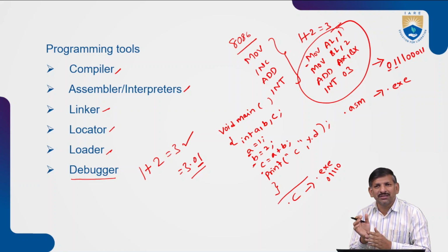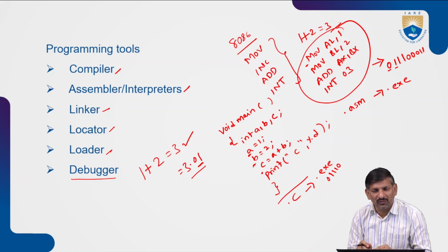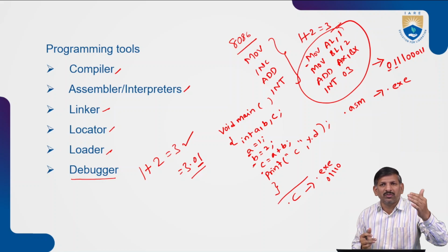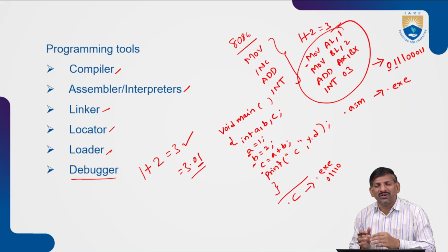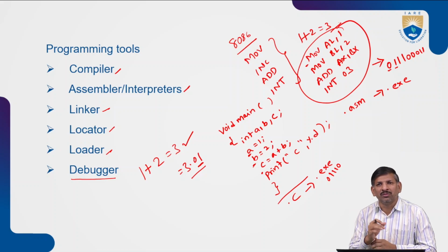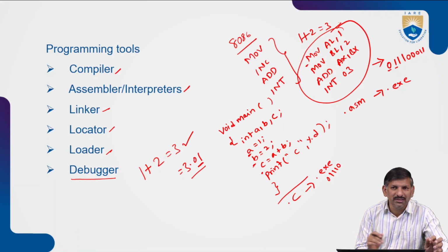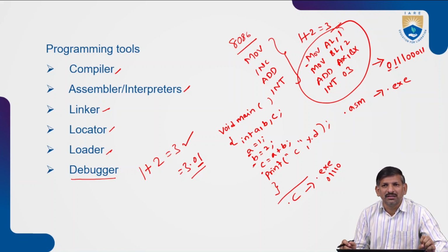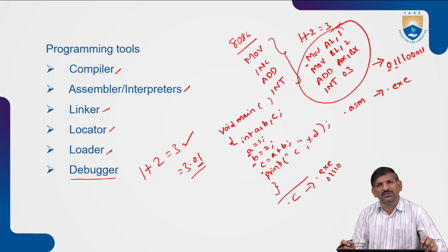If any deviation is there, we can modify that instruction. Even with thousands of lines in the program, we can set breakpoints, find the functionality deviations, and modify them as per requirement. Debugging tools include JTAG, Nexus, in-circuit emulator, and ROM emulator. These are the debugging tools.